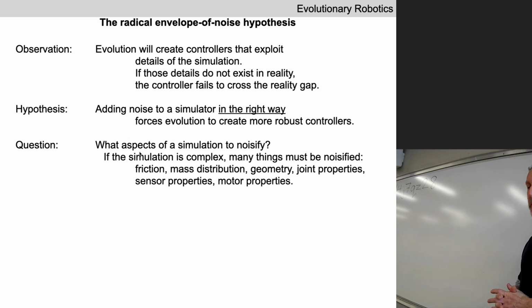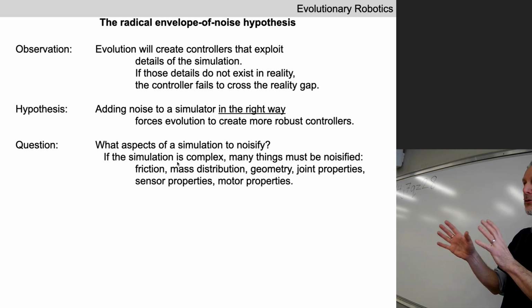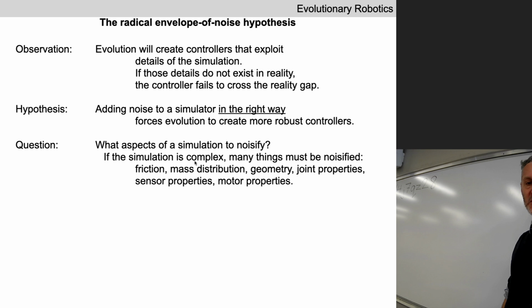However, if you think about it, the more complicated the physical simulator is, the more possible things you need to decide whether or not to noisify. You're working with PyBullet. That's sort of a middle range physics engine. It's complicated, but there are many more complicated, more complex physical simulators, which if you get them right, are a better reflection of reality. So as the simulation becomes more complex, there are more things we need to think about.